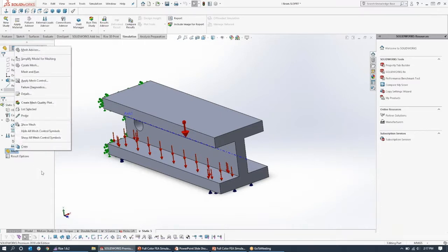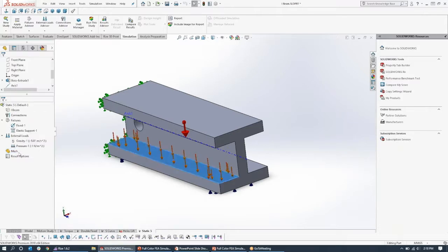and then you would want to actually run the simulation. You can just use mesh and run, and it does it in one step, and that will produce the results for you. One of the things you'll want to pay attention to with mesh is that if you have a very large or complex part, having it be large isn't all that important unless you're breaking it into small pieces relative to its overall size.